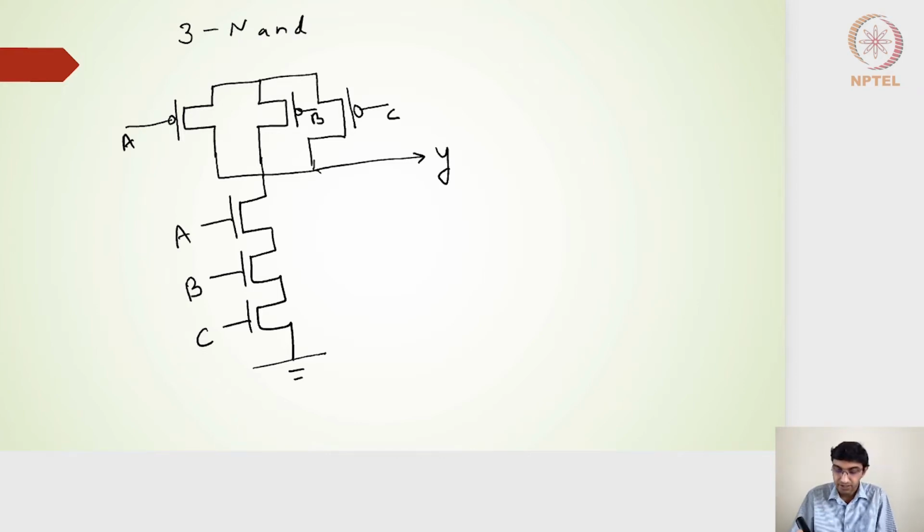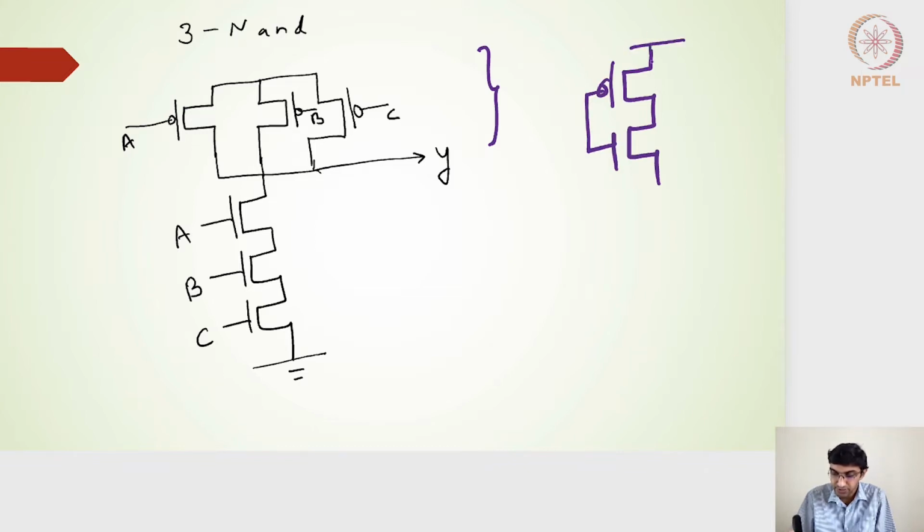As per our understanding, we need the rising resistance equal to that of the unit inverter. For the unit inverter, with PMOS and NMOS inputs tied between VDD and ground, we need a size of 2:1 to get a resistance equivalent to R.